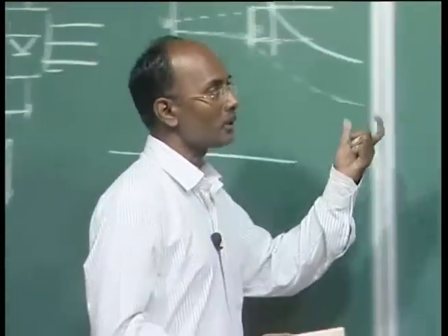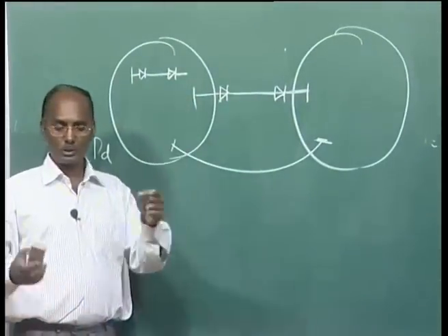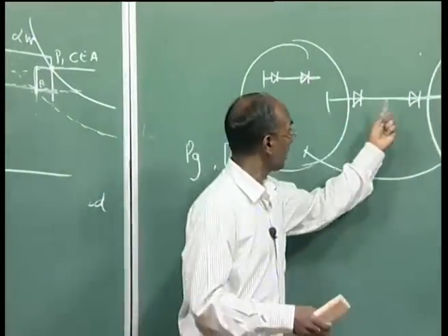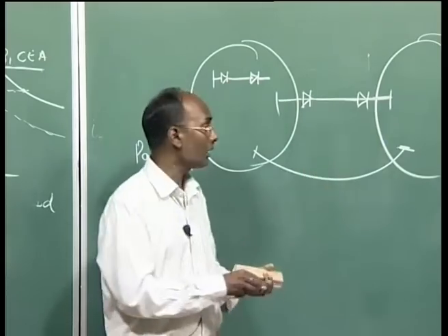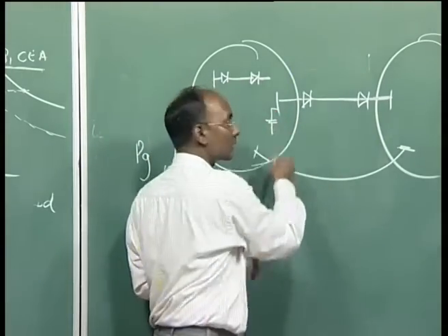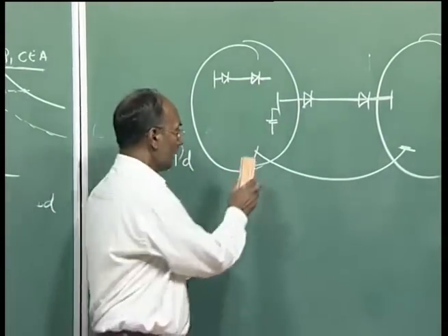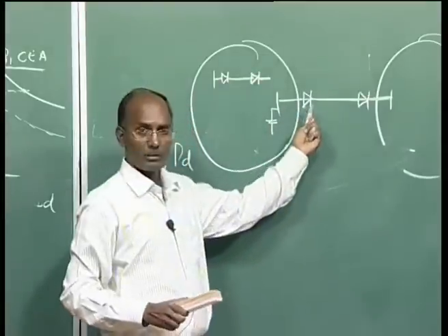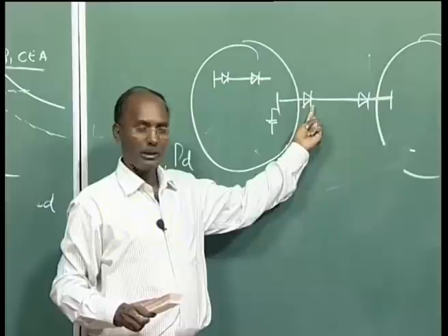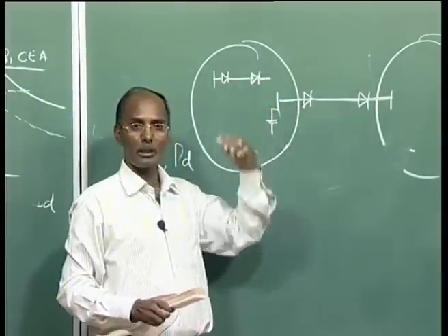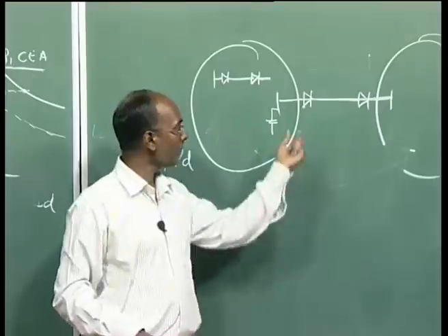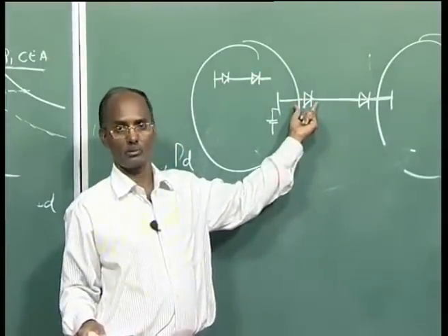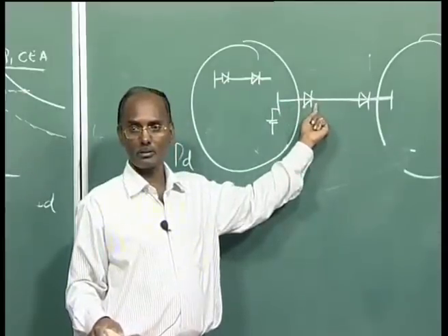Reactive power control is basically in this fashion. You know, the converters are consuming reactive power. Both the inverter as well as the rectifier require huge reactive power, and here we have some capacitor banks and other things. In reactive power control, with the help of the firing angle, let us suppose the voltage of this bus is going to be very high, you can fire with alpha at a very large value, and the reactive power requirement of this converter is going to be more. So it can consume more reactive power from here.